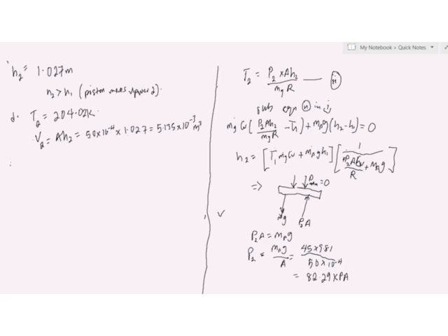The E part of the question, we are asked to calculate the change in entropy, which is equal to S2 minus S1. So we know that our Q is equal to 0 because it is adiabatic, and also the movement is frictionless. So S2 minus S1 is equal to the entropy generated due to change of state.